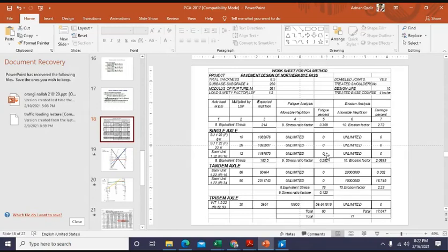And unfortunately, for this tridem axle we have this 10,000. Otherwise, as I've shown, for 30 you can have this 10,000. Otherwise, you had unlimited values, and that's why your fatigue percent due to single and tandem axle becomes total 0. But because of the tridem axle, you have some value.